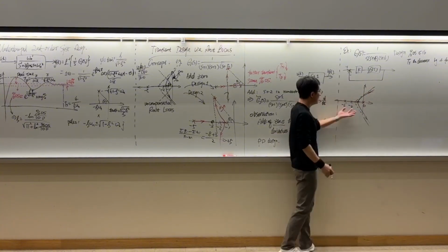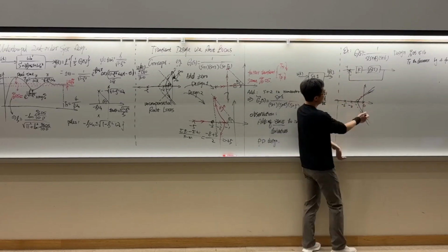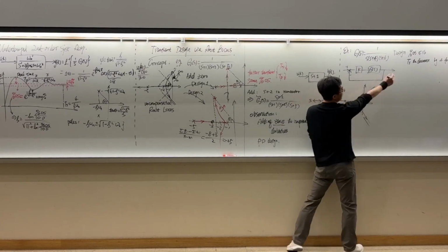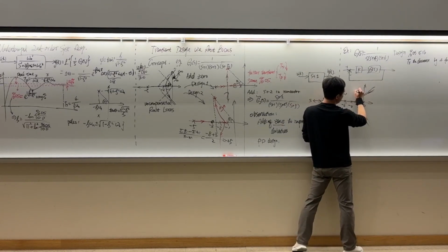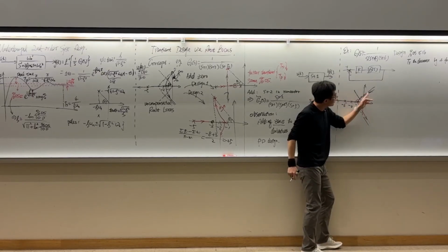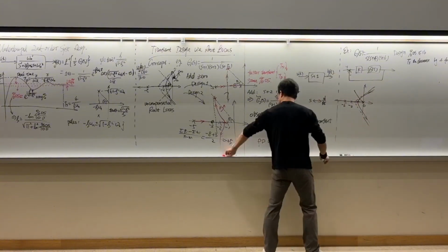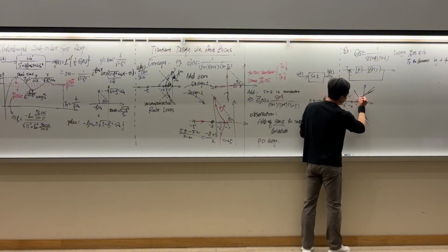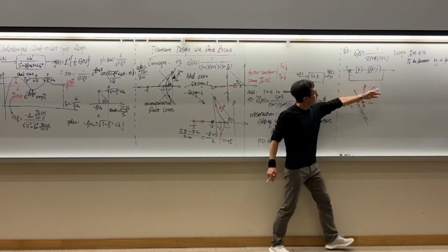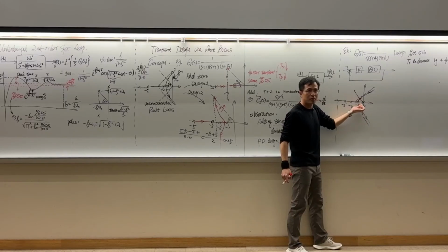All right, so no matter how you choose K, your design space is very small, very limited. You can have some percentage overshoot. Let's say a 16% overshoot is somewhere around here. So if you have a percentage overshoot of 16, that means your closed-loop poles will be here and here. So the settling time, you can conceptually understand, will be rather limited.